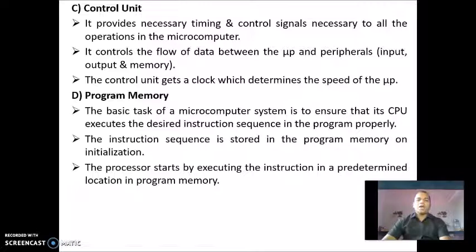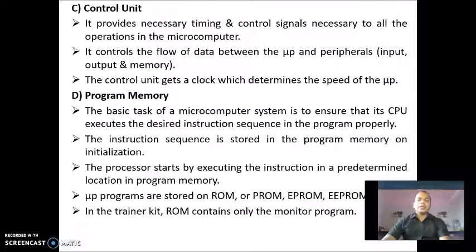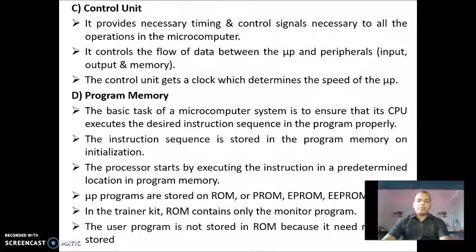The processor starts by executing the instruction in a predetermined location in program memory. Microprocessor programs are stored on ROM or PROM, EPROM, EEPROM or E2PROM. In the trainer kit, ROM contains only the monitor program. The user program is not stored in ROM because it need not be stored.